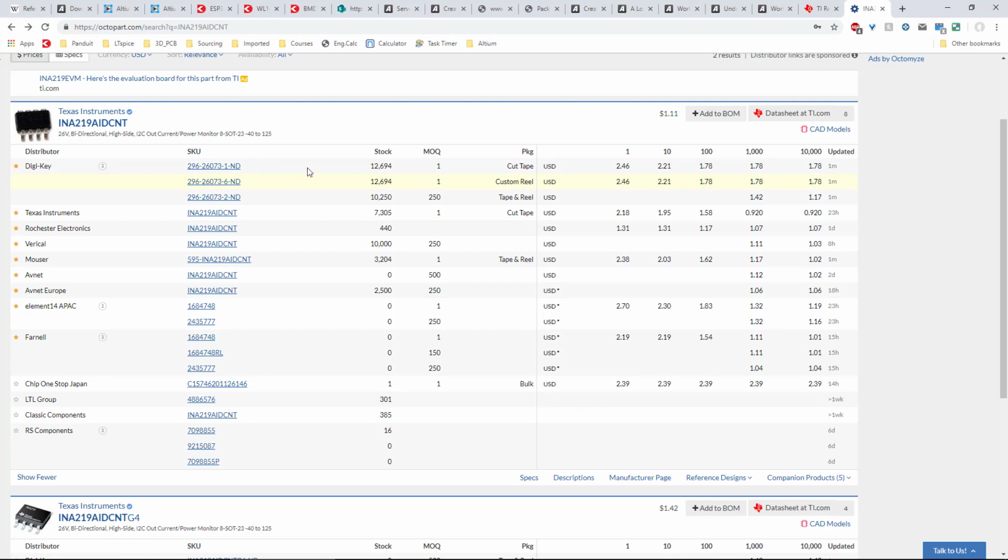So basically, just a quick comment about DigiKey. Why can I see 3 different part numbers in here? The DigiKey or supplier part number is called SPN, supplier part number, and there is the manufacturer part number, MPN. So don't mix the two. Why can I see 3 different part numbers for the same component? Let's click on it. This is a very important point when you deal with component suppliers.